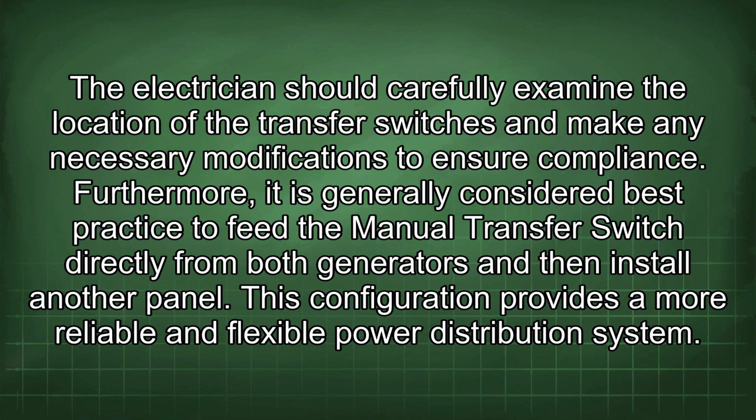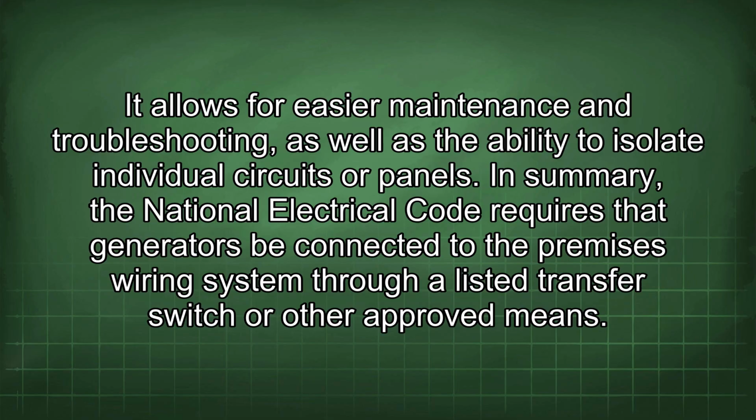Furthermore, it is generally considered best practice to feed the manual transfer switch directly from both generators and then install another panel. This configuration provides a more reliable and flexible power distribution system. It allows for easier maintenance and troubleshooting, as well as the ability to isolate individual circuits or panels.